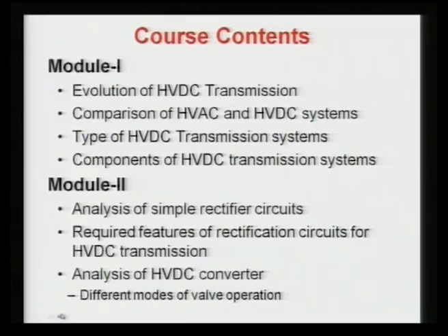To start with, in this module I will first discuss the analysis of the simple rectifier circuit. It may be the single phase rectifier circuit, and along with that we will see the 3-phase circuits. Then we will go for the various configurations, and we will see their advantages and disadvantages. We will see the various terminologies that will be used, like the DC output voltage, peak inverse voltage, and commutation group as well. Then with this terminology I will jump to the required features for the rectifier circuit operation in HVDC link.